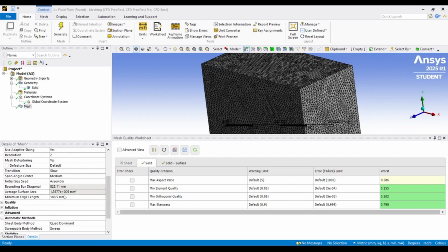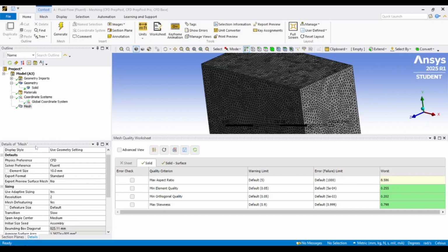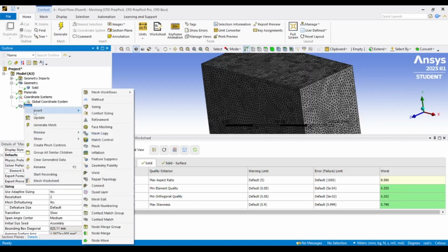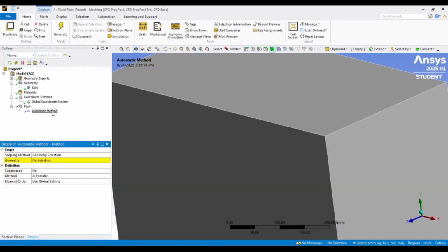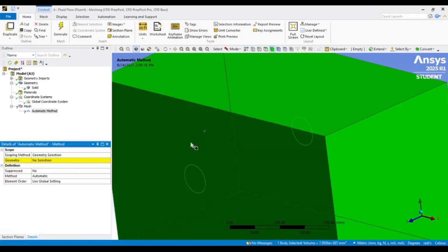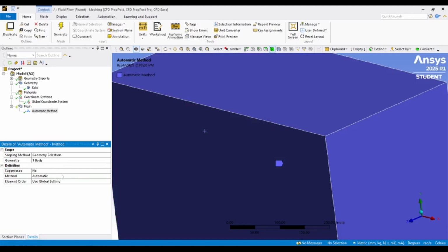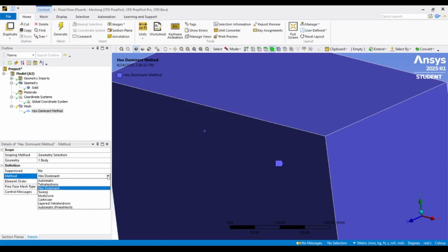If you're studying flow-induced vibrations or aeroelastic effects, you can further couple this simulation with a dynamic mesh or a structural solver in ANSYS to analyze how the cylinder responds to these periodic lift forces. This kind of fluid structure interaction, FSI, setup allows you to observe how the oscillating pressure fields cause motion in flexible bodies, which is useful for engineering applications like bridge cables, offshore risers, or turbine blades.